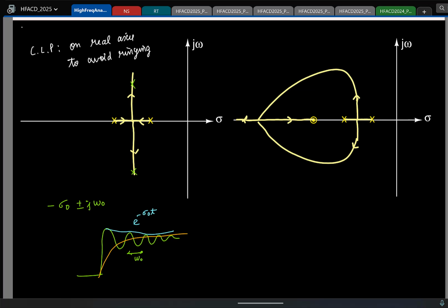So now tell me, when I introduce this left half plane zero, do you think we are doing better with respect to stability or not? Yeah, why? More left half plane is okay. Here also, that's more important, right? We wanted the closed loop poles to lie on the real axis, correct? When I didn't have any zero, this was not doing anything. It was just going to infinity. But the moment I have a zero, the zero is acting like some kind of a magnet. It is not allowing the poles to branch out to infinity along the S-plane forever. It is making them fall back on the real axis, making the system more stable. Okay? So this is another takeaway we can have. A left half plane zero, I will say, is good for stability.